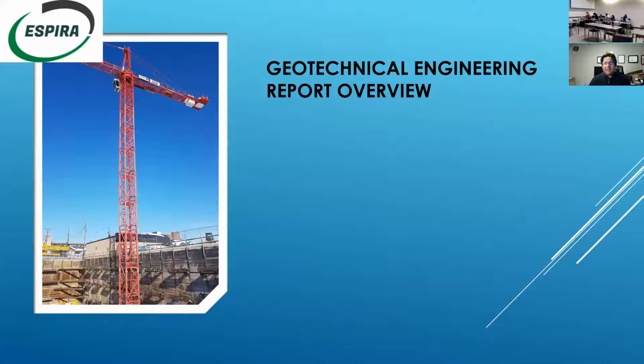Typically, a client of the geotechnical firm sends out a request for proposal, and the geotechnical firm comes up with a scope: how many holes, what depth, how many samples, SPT at different depths, and the cost to complete the investigation.